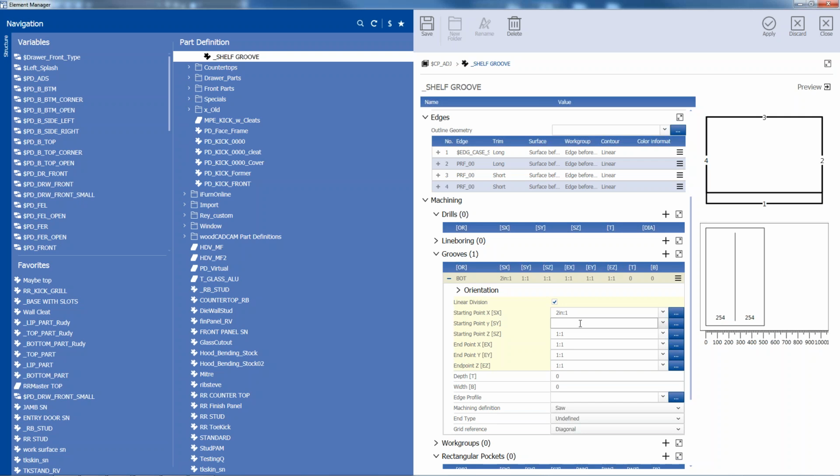Okay, gotcha. So it's 4 inches wide by 17 inches long and however deep. And 1/4 of an inch deep, so it will host a metal bracket. All right, so it's really more of a rectangular pocket than a groove. Let's do it as a rectangular pocket, not a groove. Get rid of this groove.